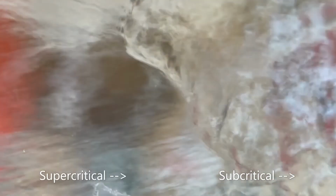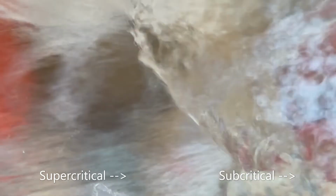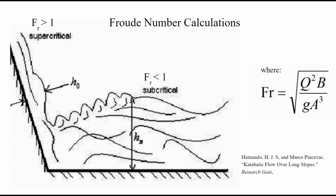Our initial research indicated that we could simulate this open channel by dropping a supercritical flow into a subcritical flow. Supercritical flow is defined as having a Froude number greater than 1, whereas subcritical flow has a Froude number less than 1. Given our desired size for classroom demonstration and the flow rate we felt was attainable, we used these parameters to design our demo.